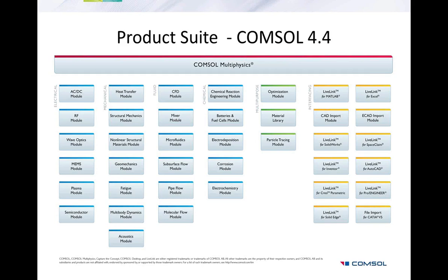I worked with pulp for 9 years, but I guess the simplest way is just to try to use one of the non-Newtonian models. It's very difficult because there are no really good models for pulp. But if you settle for a non-Newtonian model, you can use that to simulate pulp.